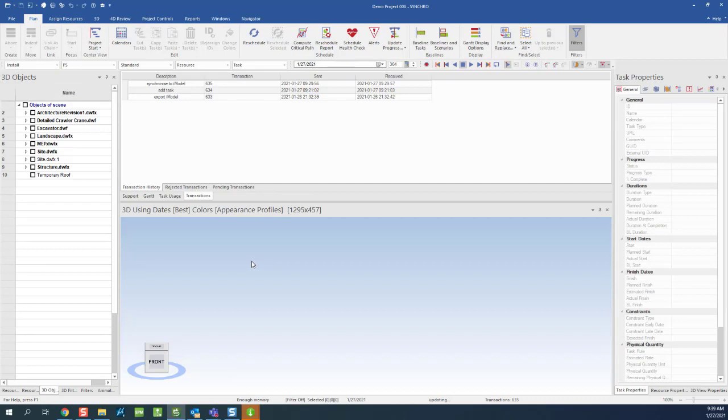And in a larger picture, we will eventually be using more and more of the iModel bridges, because it is definitely a more streamlined format. It's going to give you better performance in SYNCHRO Pro as well. So besides the couple of limitations I mentioned, like if you already have an existing file you're working with in SketchUp, I would recommend using iModel bridges wherever you can.